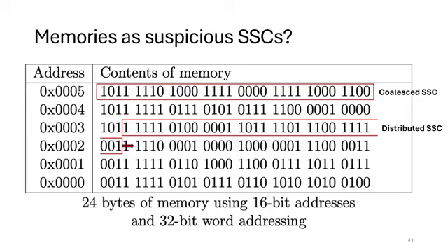Memories, because they are a list of registers, can also be used as part of a ticking time bomb Trojan. The data flow graph is also created for memories by Bomberman, and each block of addressable words is treated as its own saving state component. If there's word alignment mandated by the system, then it will just create one block for each addressable word of memory.